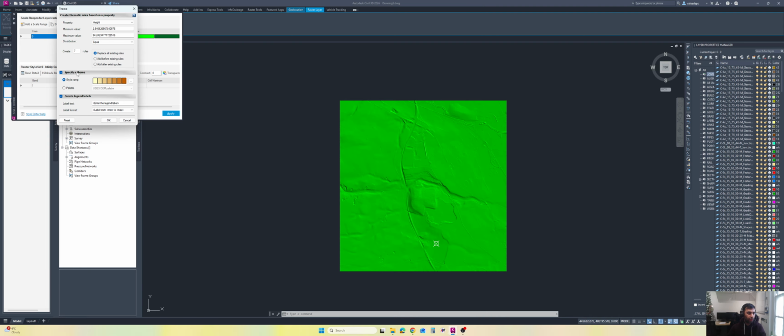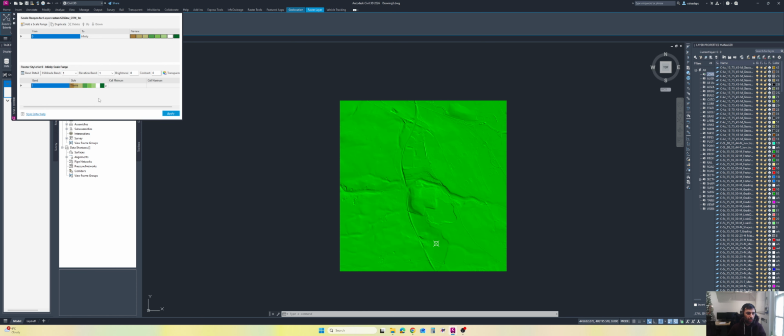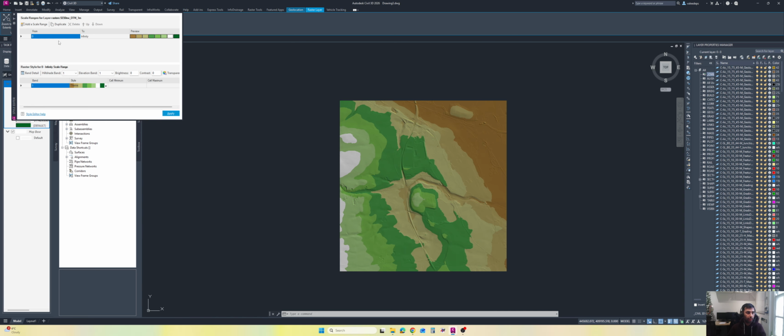They have different styles, whichever you like, so I will go for the palettes and go for the USGS DEM palette. I like this one. It depends on you, whatever you like. You can see it's a range of colors. I will go with this one. So I have this theme. I click apply. So now you can see we have different colors with different elevations.